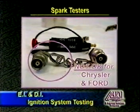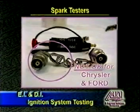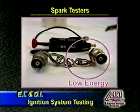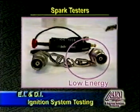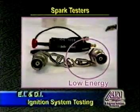However, on a Chrysler DIS system, that Chrysler coil pack doesn't pack the kV potential to fire 2 of the ST125s clamped together. So if you look on the right, this is what we call a low energy spark tester. You can see the center electrode protrudes out a little bit, and this spark tester requires 15 kV. So for those of you who like double stressing coil packs on Chryslers, you want to make sure that you do not use 2 ST125s, rather use 2 of the low energy clamped together. That gives you a kV demand of 30 kV, which the Chrysler DIS coil packs have the ability to do.